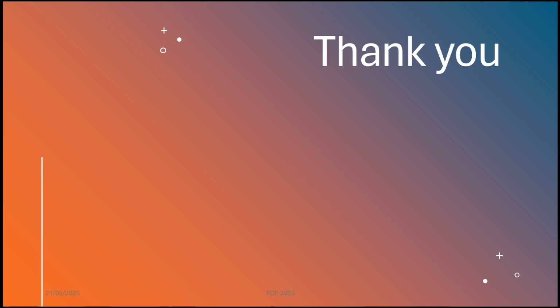When you break down your design, maybe instead of breaking it down after you completed it, you want to do that on the go. Meaning, okay, I need to build this complex design. It is made of 3 modules because I plan it that way. I bring up module 1, and I realize that I can do some simple verification because that's not too complex. Maybe I can even use formal. Let me try to write some properties around it. And you do that, and then you move to the others.